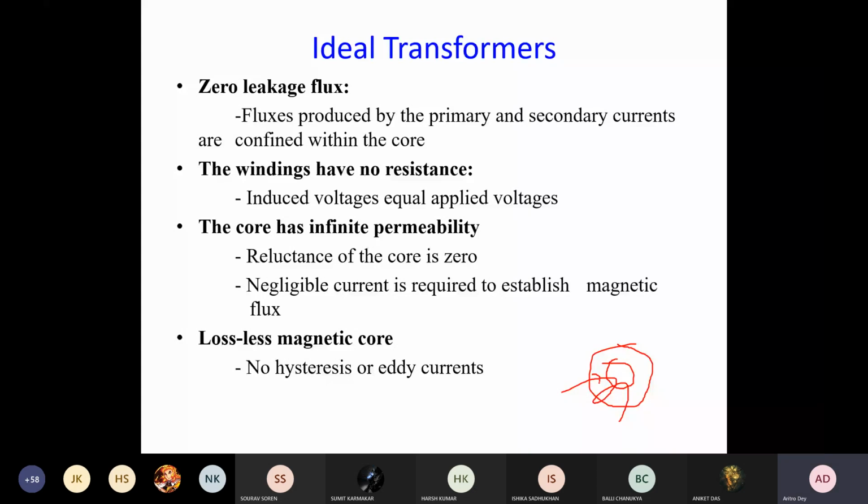Yes, so there is a coil, and when an alternating current or any current is applied, there will be a flux, right? Most of the flux will be linked with the magnetic material, and the rest will pass through the air. So this is your leakage. Leakage flux is assumed not to be there, but practically it is not true, as we'll see that leakage flux is there for each winding, for primary as well as secondary. And we will represent that leakage flux in terms of leakage reactance.